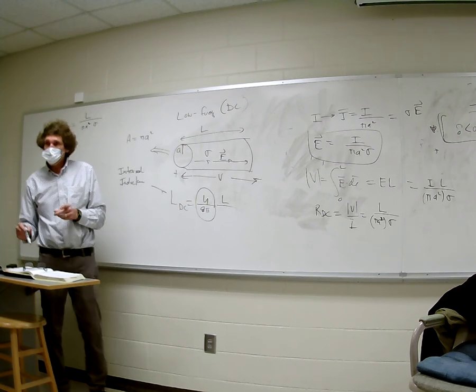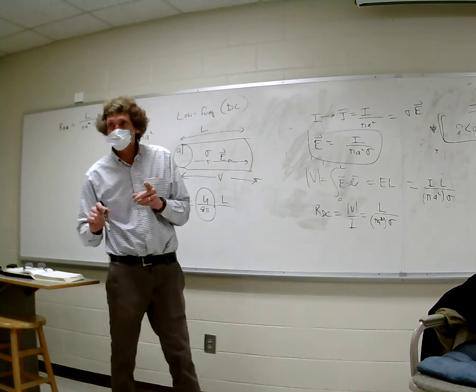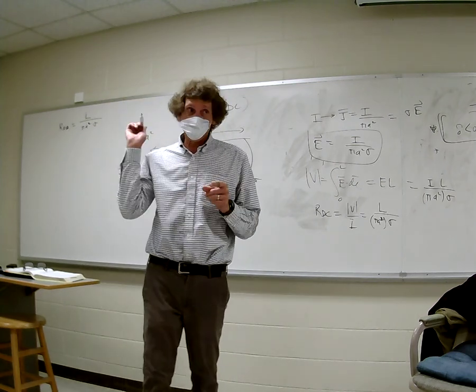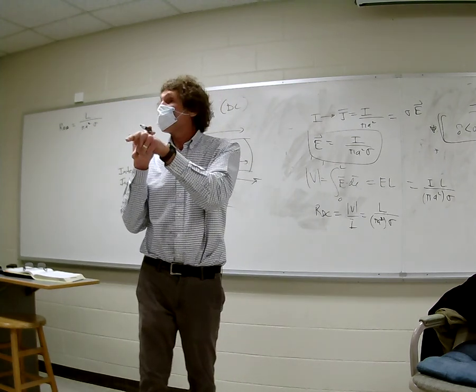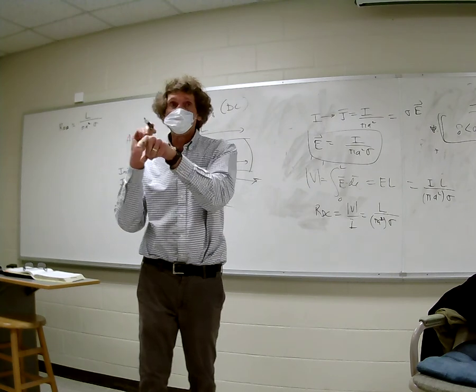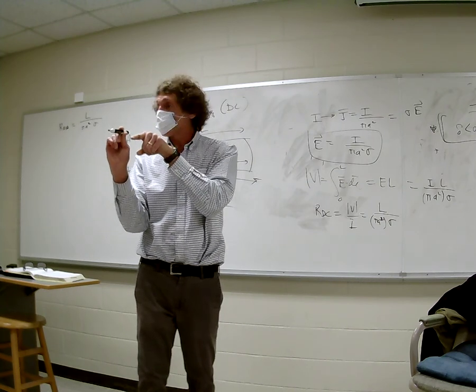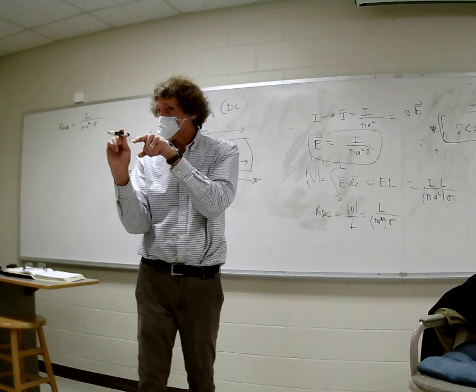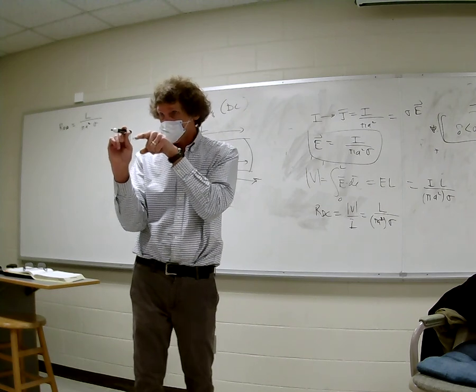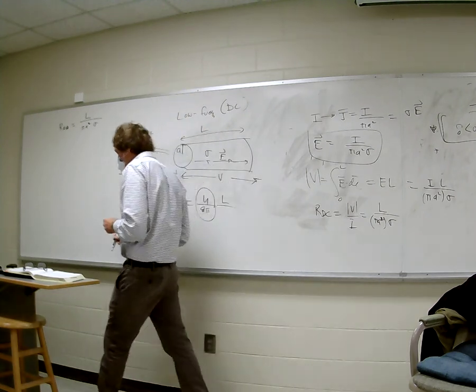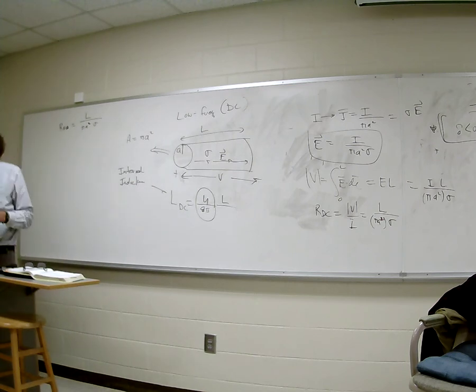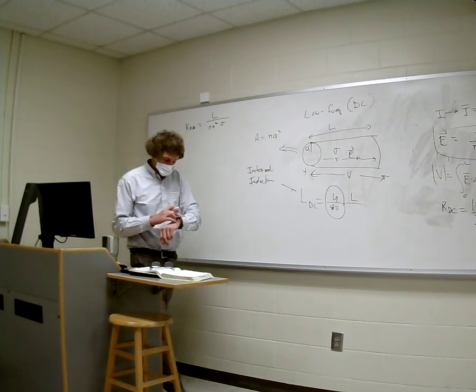But the real problem with estimating inductance correctly, there's internal that we have, but how is the return current getting back to the source? That return current creates another H field that cancels a lot of the original H field. So they can't give you an inductance per meter for the external wire. It depends on things that are in the environment, and there's a whole different school of thought on how to do it. It's called partial inductance that Dr. Wentworth just mentioned, and I don't want to get into it.